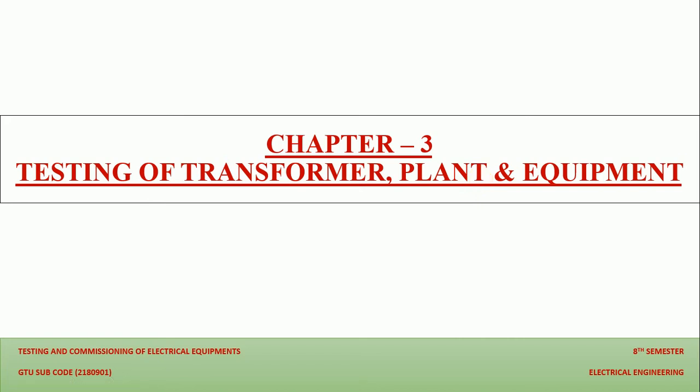And then we discussed in detail the three-phase transformer connections, in which we saw the two basic connections of transformers, star and delta. Then we discussed the different arrangements and phase groups of transformers for successful parallel operation, and the different connections that we establish to get our desired voltage and current from the transformer.